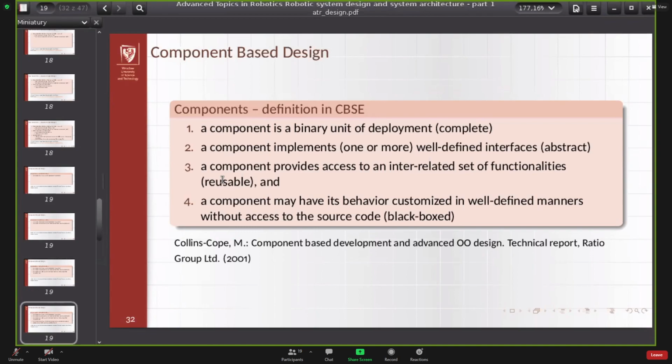So when you want to connect a different LiDAR to your software, you change the ROS node from the LiDAR that you had, for example, from SICK to the LiDAR that you have from Hokuyo, but the type of message you receive is exactly the same. So you don't need to change anything in the other part of the software, because the interface is exactly the same.